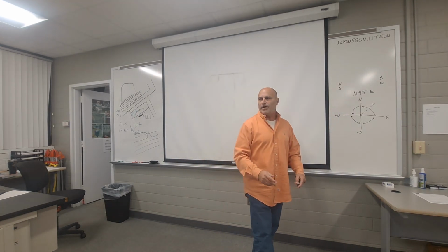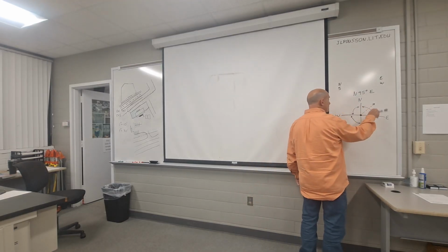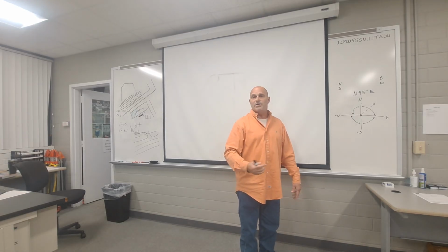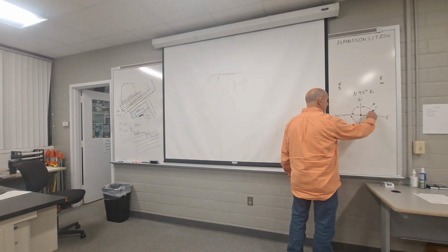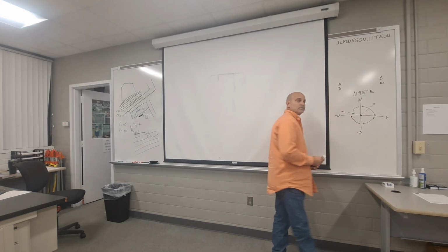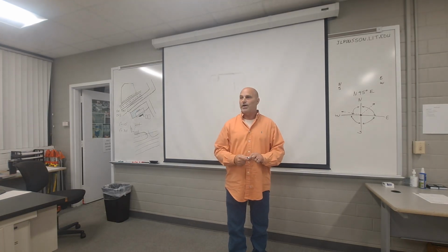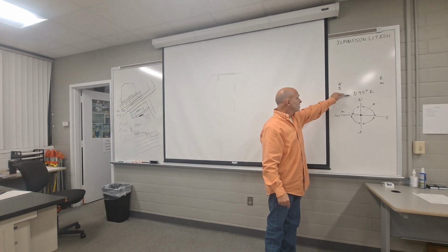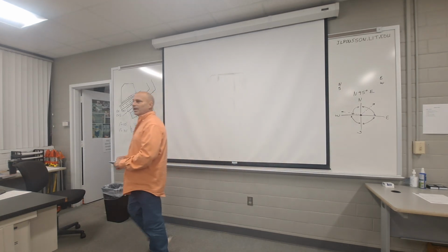Zero is to the right. We count counterclockwise. Azimuth says north is 0 degrees and you count in a clockwise direction. So instead of something like that, I could tell them in azimuth, go to 273 degrees. 0, 90, 180, 270, 273 degrees would be that direction in azimuth. We're not gonna be getting our angles like that. Our angles are gonna be in what AutoCAD calls surveyor's units, always starting with north or south, always ending with east or west.